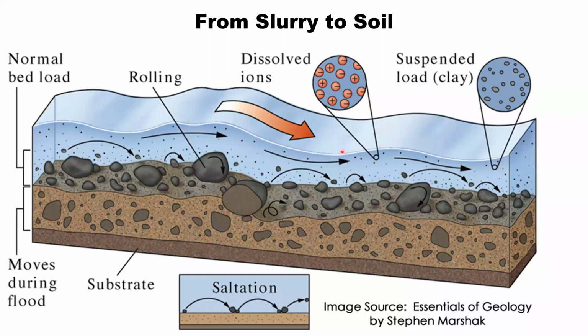Our process is really one of saltation along the bed, where smaller particles, but large enough that they cannot be carried as suspended load, are going to bounce around on that bed of material, on the substrate and on this surface, until they find a spot where they get locked in place. Our suspended load is going to continue to travel with this fluid until the fluid velocities reach near zero values. In other words, when this fluid reaches the pond, the finer materials can finally settle out.